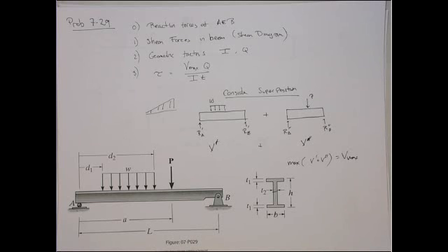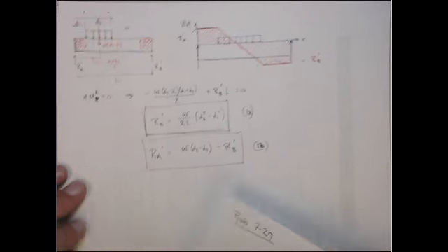What I'm saying is, if there's an error in the way I derive the equations, and I use the same equations to compute the transverse shear with the numbers, it'll have those errors in it. Whereas if I do it with a different approach, like our general approach, an error in the equations or the implementation of the equations will be picked up. So it's a good trick for debugging, all right?